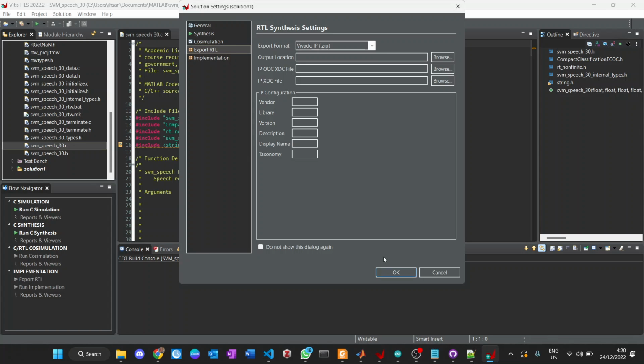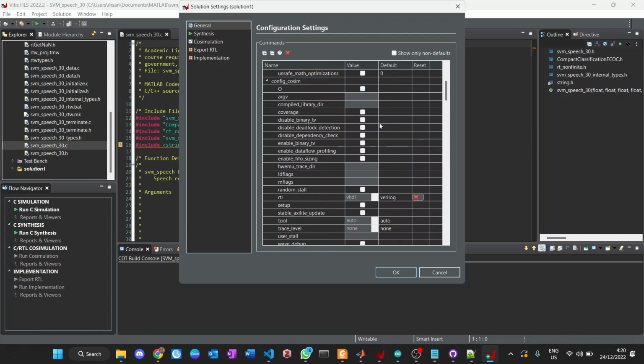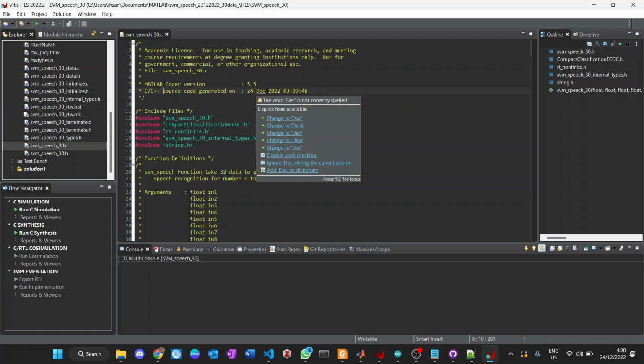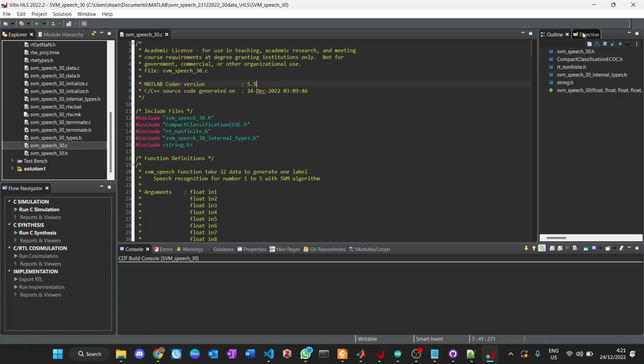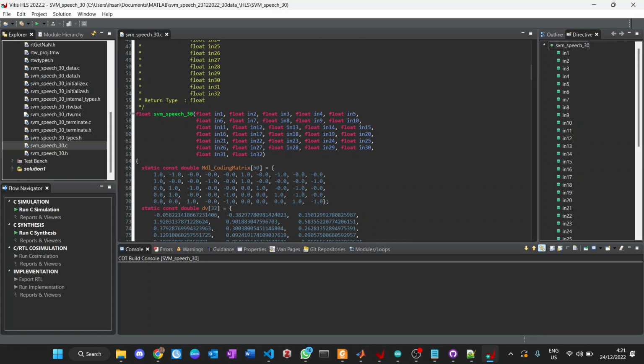And as we said later, you can ask and then search in Google what is the parameter that you can set instead of this. Here what I usually do, I specify the directive. Here we have the input of 32 data with a float type, then the output return with the float type. I don't want to make this a digital port input because it takes a lot of inputs, because float is 32-bit, then 32 by 32. It's a huge number for ports.